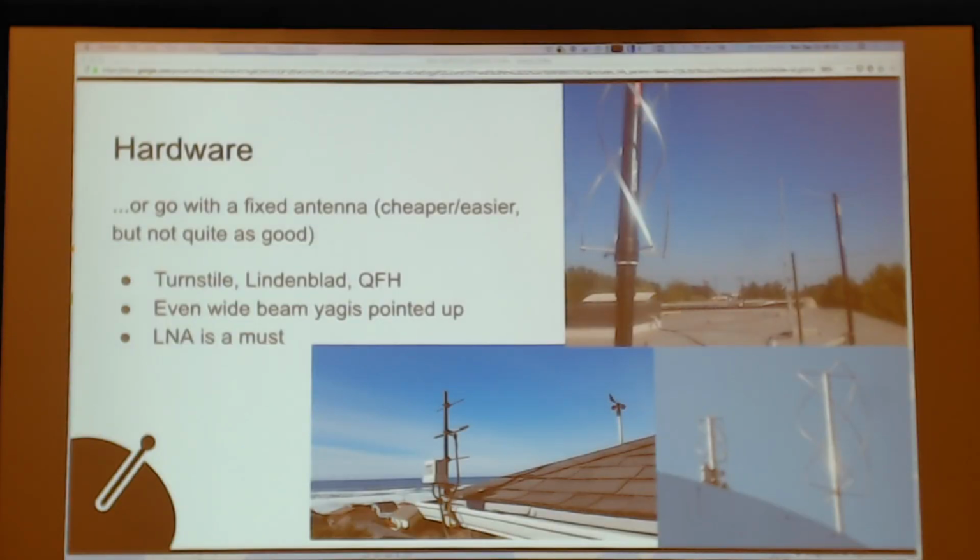All right, so if you want to start, you might think of building the rotator, maybe the 3D printed rotator that we have, but that's actually maybe not the best way to start getting into SatNOGS. Just start with an Omni antenna. If you have something on your roof, you know that on the RF side you're going to be disadvantaged, right, from a 40-element Yagi or something. So you kind of know what to expect for receive performance. But the rest of the system you can get bootstrapped and going using an Omni antenna.